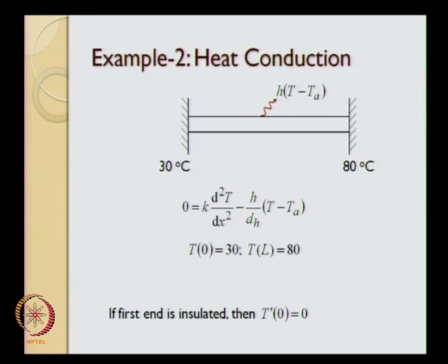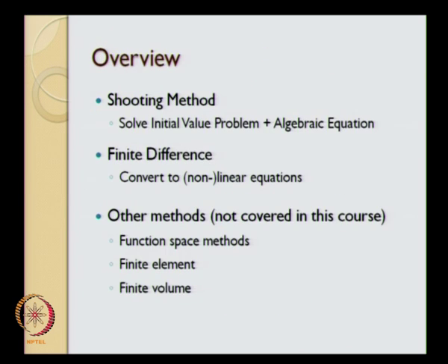Then we took up the second example of heat conduction, and this is the example that we solved using two different methods, the shooting method and the finite difference algorithm. A final piece of statement about the two: the shooting method, as we saw, does have certain limitations but is relatively simpler to use compared to the finite difference algorithm. That is because ODE initial value problems tend to be easier to use, and there are certain softwares available to solve the ODE initial value problem. However, the finite difference algorithm is a much more powerful method to solve a general